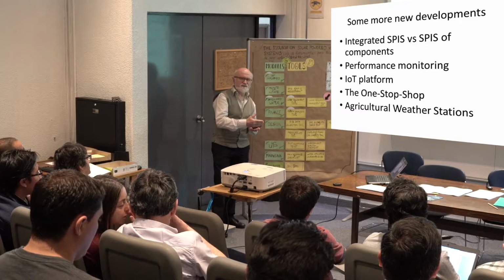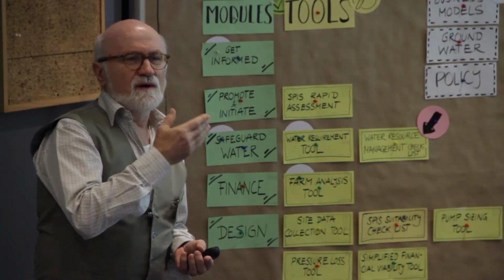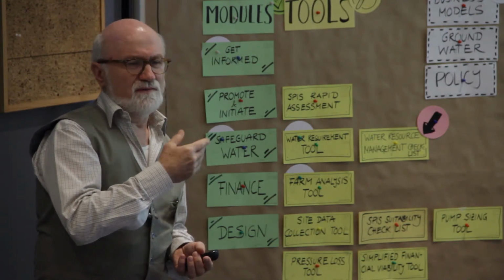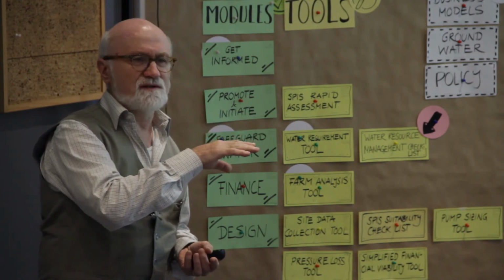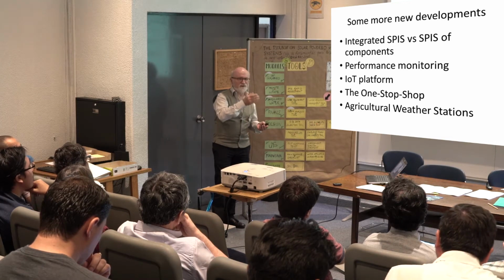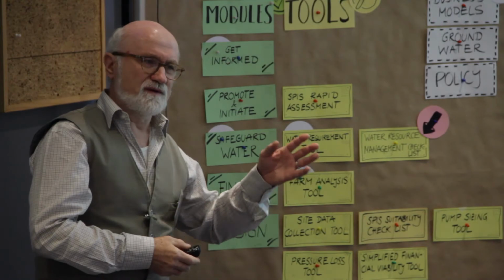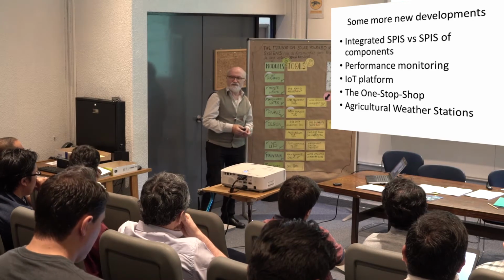And what I think is important and probably will come, we have many meteorological stations for different areas, and I think there will also be agricultural weather stations. They might grow test fields with the 3 main crops in the area, and they can tell the farmers every day how much they have to irrigate, because they have the weather data and they have their test fields. Then they can tell you today and tomorrow you irrigate, I don't know, 30 cubic meters per hectare, and in the next days we'll give you more information when we have our weather data calculated.